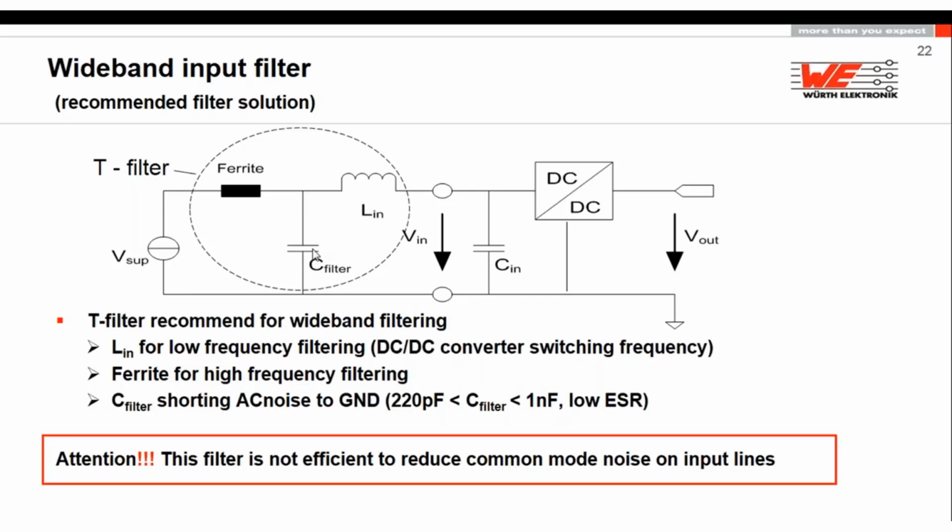In this area, if you put a 100 ohm, maximum 300 ohm ferrite bead, you will be much happier, because with less layer capacitance you will automatically have a much better bandwidth. You will cover much more frequency and the efficiency will be good enough. A 2 kilo ohm one makes no sense because it has 2 kilo ohm but a very narrow bandwidth. All that is only because of differential mode noise.